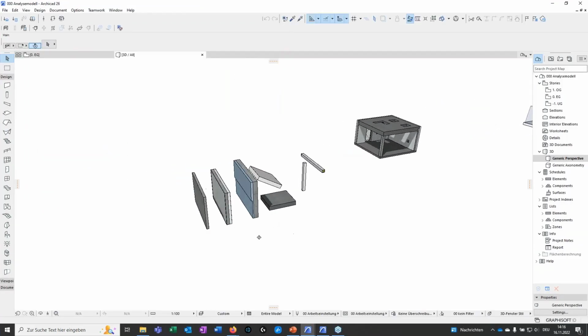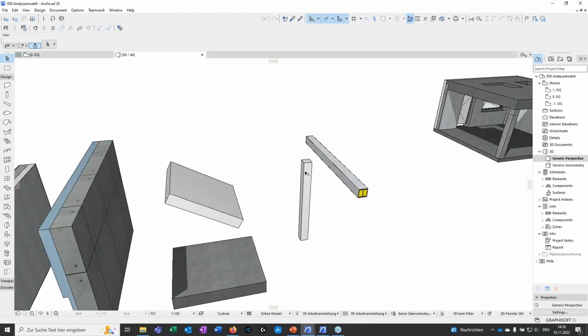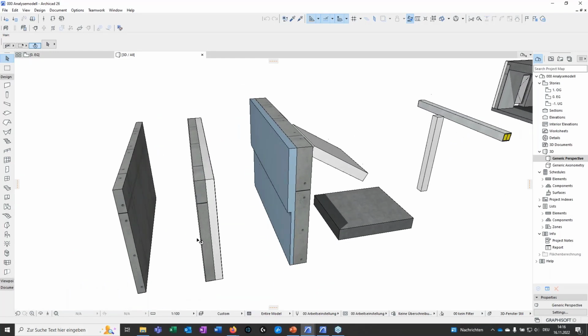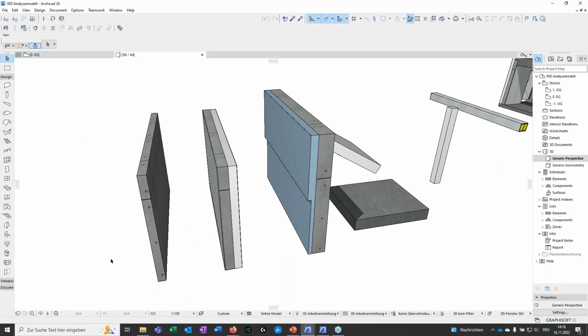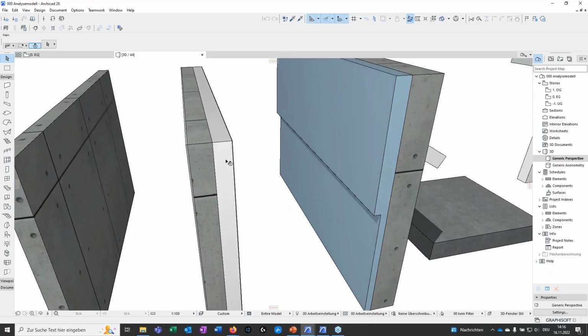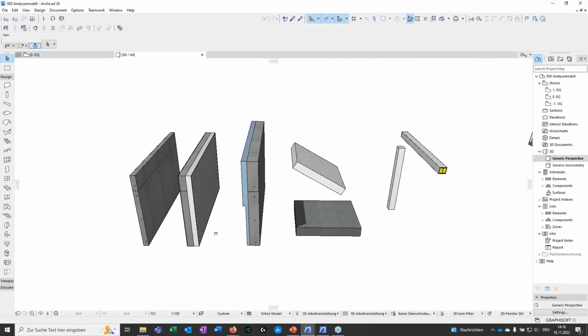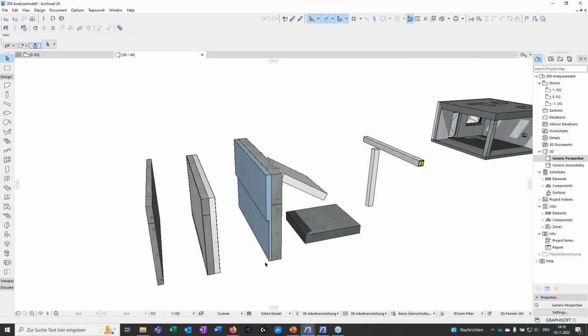In Archicad, we have several different elements. We have walls, slabs, roofs, columns, and beams. And every one has a core. One material is one material, but we can also have different materials in one wall. And one thing, the concrete is always the core, and it is called like that in the model. And so we can translate this geometry to surfaces, and columns and beams to beams.